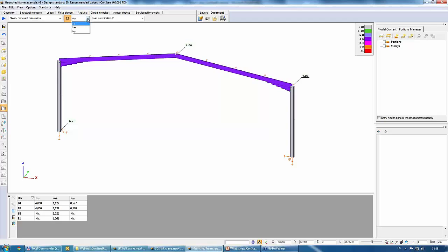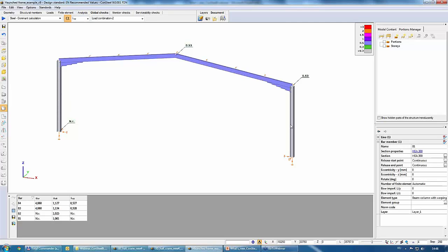And we can check the alpha ultimate values in each member, and finally the slendernesses of our members, which are the base for the calculation of the reduction factor. Of course, it is still not relevant for the columns, and only the beams are evaluated for stability.